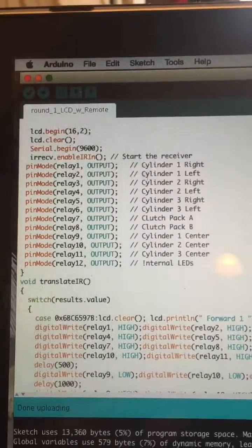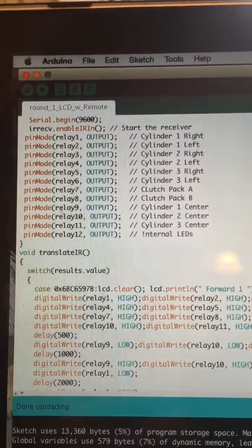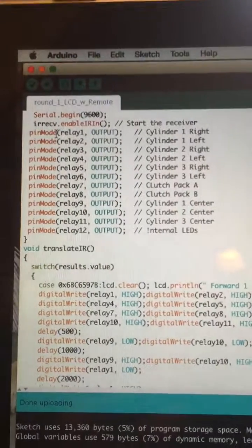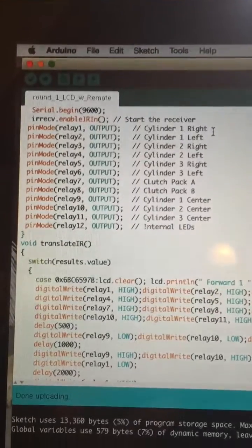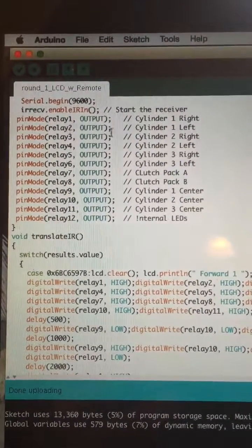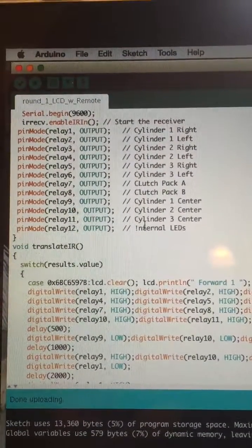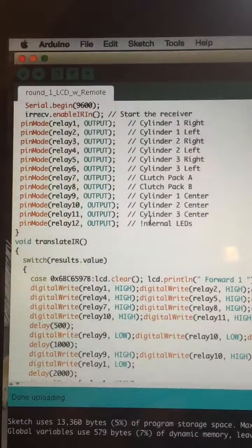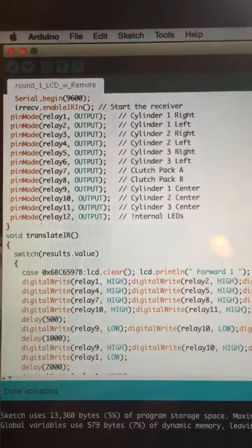So I put in a pinMode command. That's just saying that that pin on the Mega board can be turned on or off, kind of as the computer sees fit. So we have pinMode, and we're calling them all outputs, meaning that the board will turn them on to 5 volts or 0 volts, and it won't receive any information or any data on that.